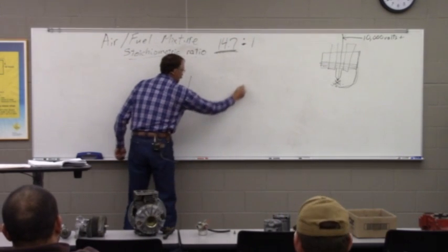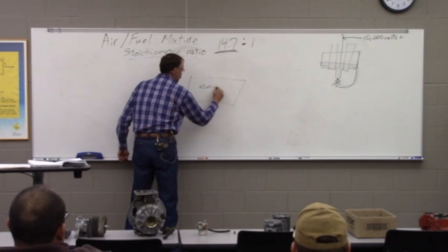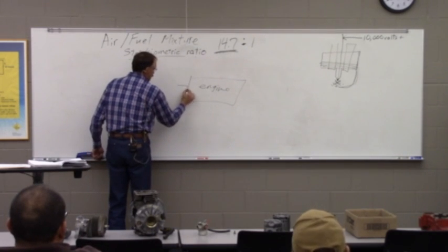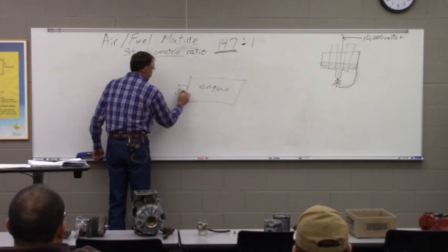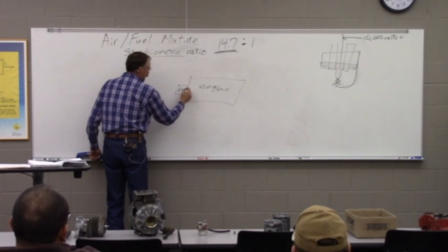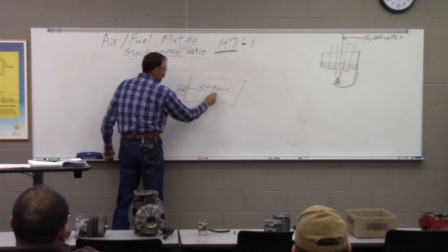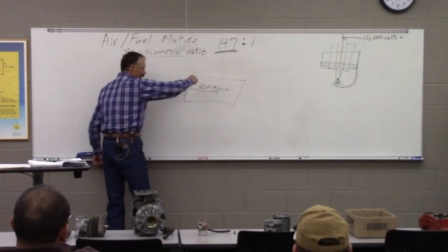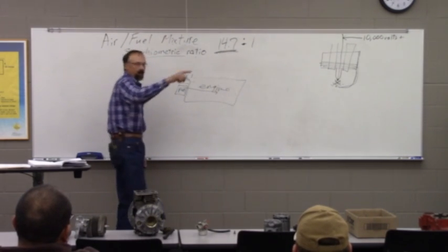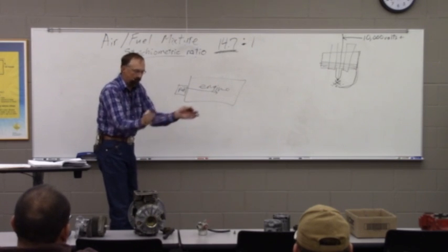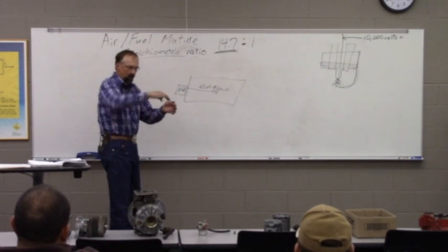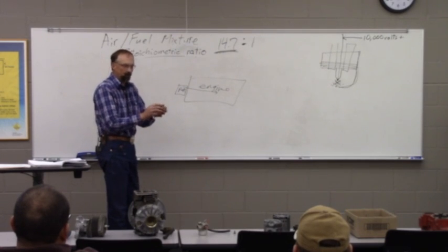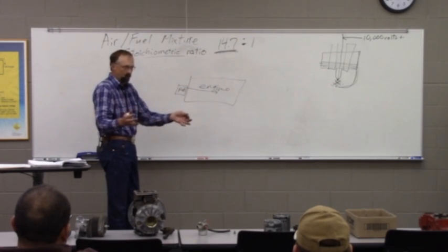So there again, if this is our engine, most all engines on the front end of them are going to have a pump. That pump is going to push the water back into the engine around all the cylinders. We were looking at it out there, how it goes around all the cylinders. It goes over the top of the head. All the excess heat we're making in that cylinder, we're transferring it into the water.